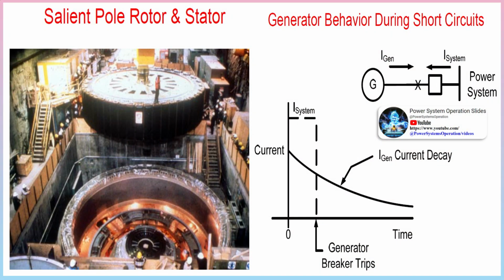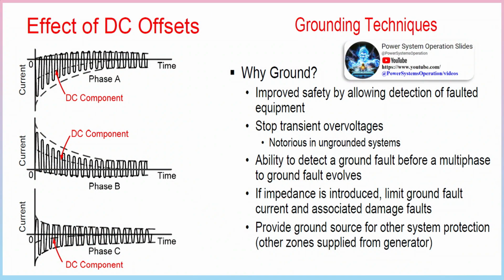Types of generator protection. The various forms of protection applied to the generator can be categorized in two manners: protective relays to detect faults occurring outside the generator, and protective relays to detect faults occurring inside the generator. Other than protective relays, associated directly with the generator and its associated transformer, there are lightning arresters, overspeed safeguards, oil flow devices and temperature measuring devices for shaft bearing, stator winding, transformer winding and transformer oil, etc.